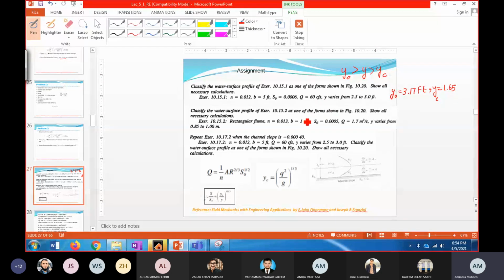Excuse me, ma'am. And there is an issue with the Manning's equation because we have been taught that if you're going through the SI unit, the formula is 1 by n. If it's the FPS system, then it is 1.49 divided by n. Yes, you are right. When it is in the British gravitational system, you'll be using this 1.49.